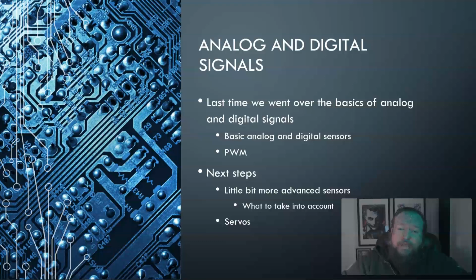We also learned about PWM, pulse width modulation, which mimics an analog output on a digital pin, allowing us to do things like fading. So far we've seen fading an LED, but you're going to see later how this becomes important for some of the other sensors that you hook up, especially external control boards, and even things like servos, which we talked about as basic motors.